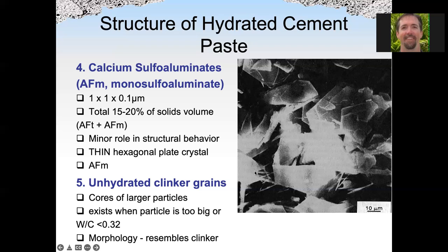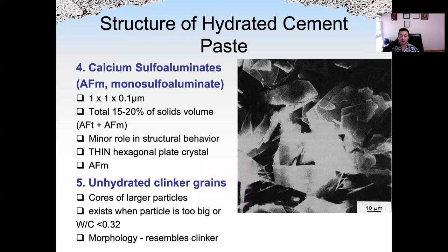I have a question about the clinker grain. You mentioned that eventually water will evaporate out of the concrete. Can it go the other way around? That is, eventually water can penetrate in and hydrate those grains, or no? If the concrete dries out totally, actually, if the relative humidity inside the concrete is below 80%, the hydration, the chemical reaction, will stop.